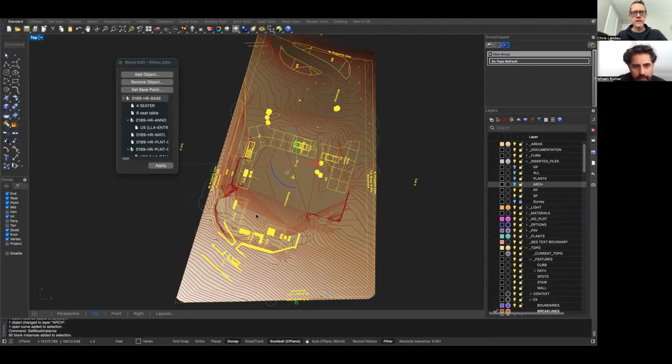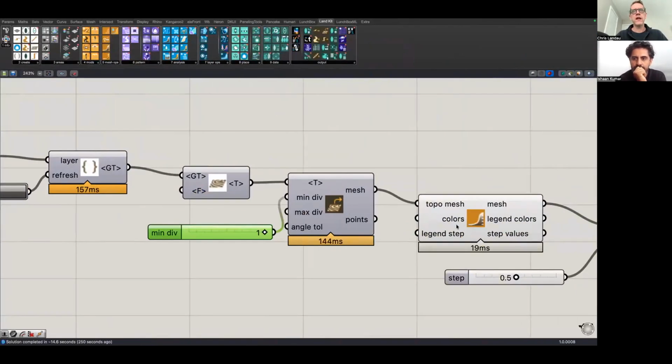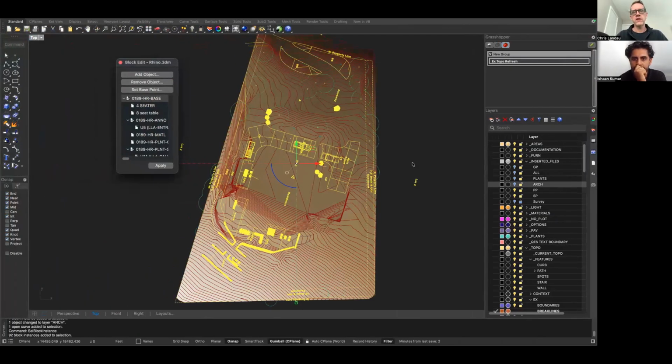Okay, let's copy some of this into, oh yeah, those walls. Okay, cool. And then there's another file, the base file, which will have the stairs and the walls. One thing I don't want to do while I'm in here in the block is refresh, because it's looking for different geometry. It's going to be confused. It probably will just not work, but in some cases it can freak out. Like if you're looking for something on a certain layer and then there's more geometry inside the block, it can freak out. So just something to know about.